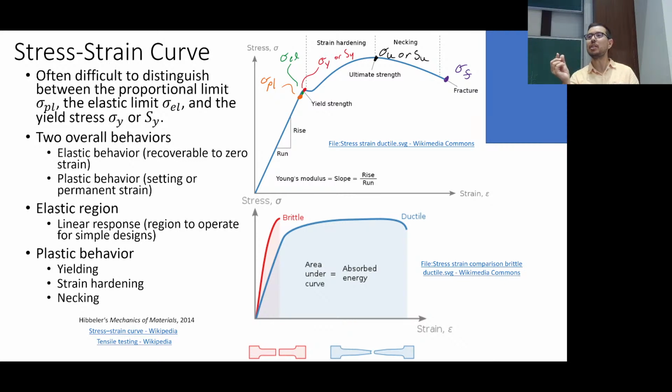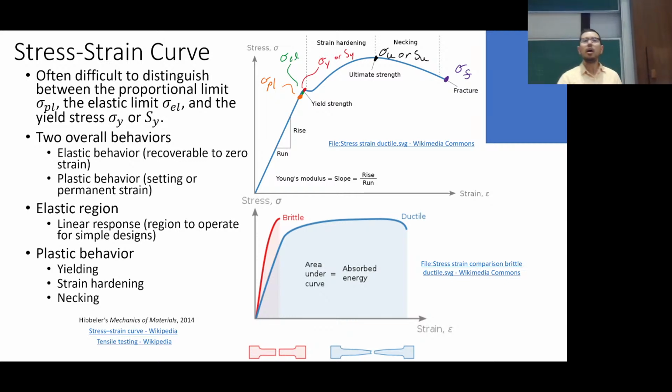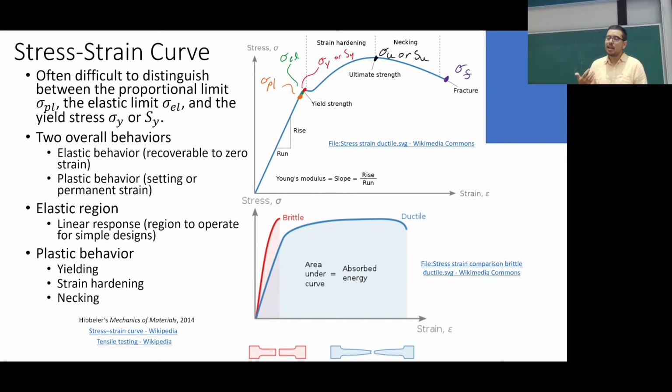Because the strain is really small. Remember we were saying 0.1% is what you have for these metals? So you'll find that the stresses we calculate are maybe on the order of tens of megapascals. And a lot of times the yield strength, once you get to where it starts to yield, and we'll have slides on this, is going to be hundreds of megapascals. And then the elastic moduli are tens of gigapascals. Giga is 10 to the 9. Mega is 10 to the 6.